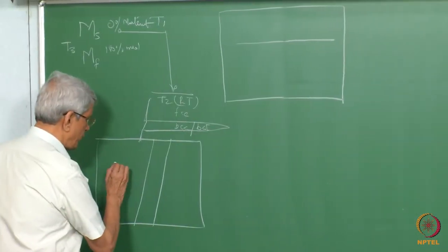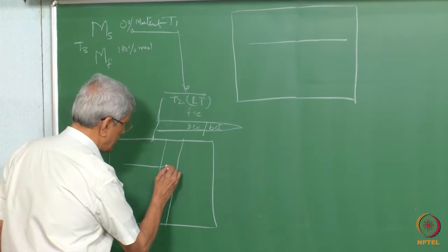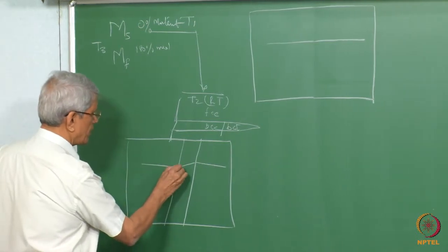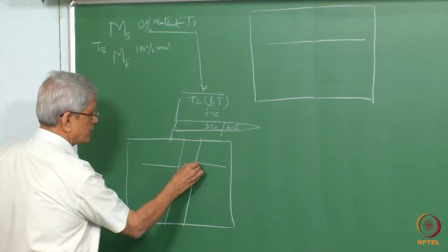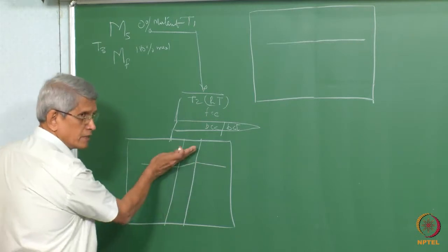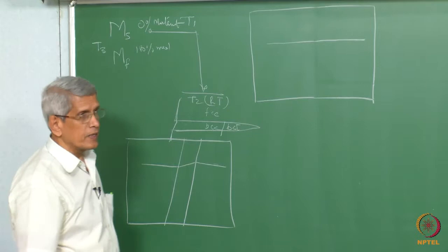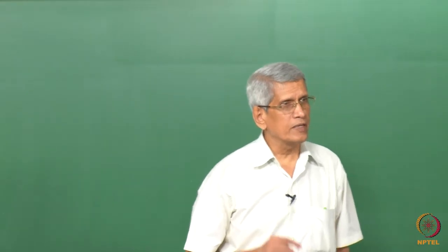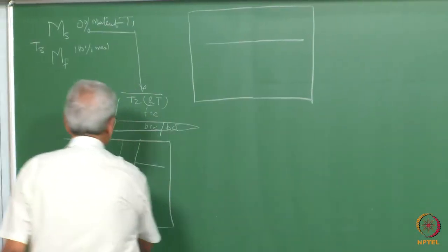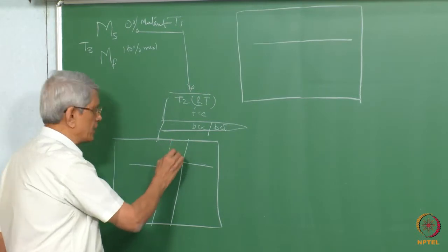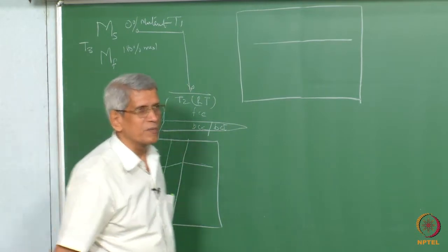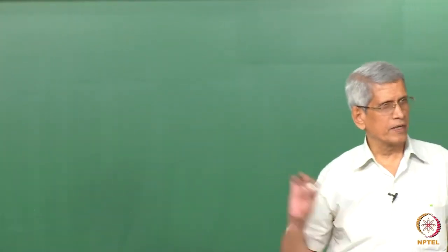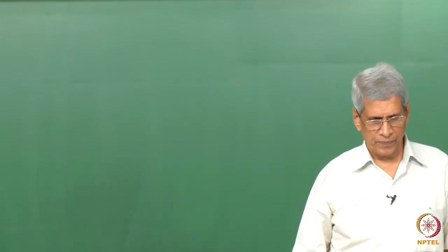After the transformation, one could see that this line remains straight up to here. From here to here, it is again straight, though it has changed direction, then it goes straight again. That means the same thing happens as in twinning. The deformation appears to be a homogeneous deformation occurring parallel to this interface possibly, correct? That is one surmise we can make looking at this microstructure.